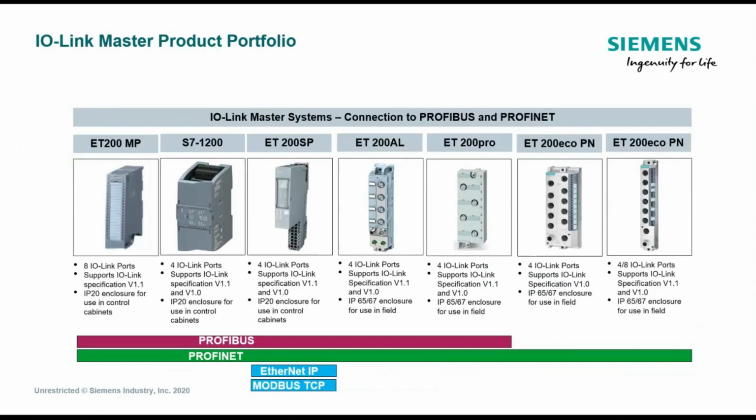It's not considered a COM module that traditionally would sit on the left side. So if you needed more I/O link connectivity, you could easily just add more and more of these COM I/O link masters to the side of the S7-1200 CPU. I've got quite a few customers doing that now on several different applications on smaller machines. Works like a champ.